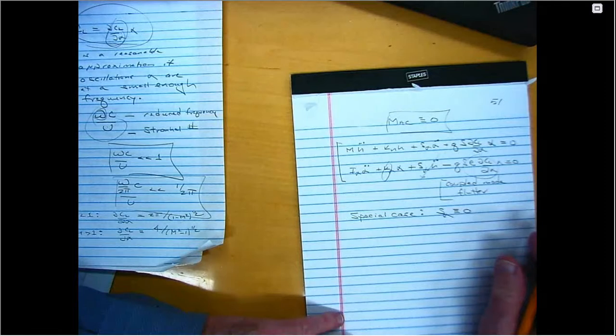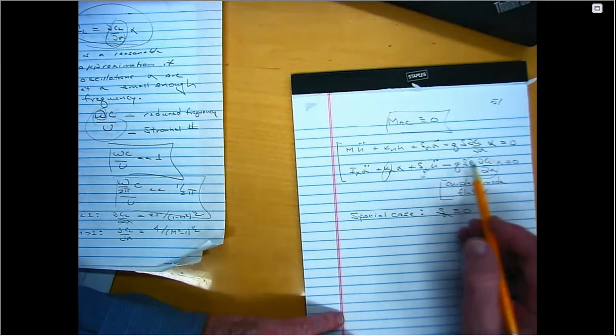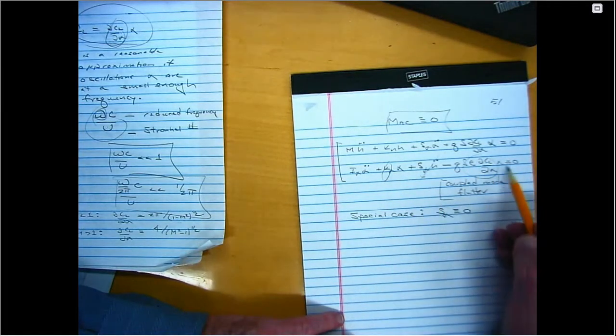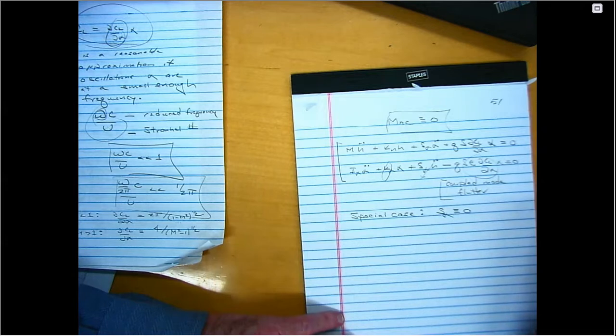What about single degree of freedom flutter? Well, I mentioned that the other day. I'll just remind you of this. If I have single degree of freedom flutter, the only way I can get that is if in this term, even with S alpha 0, in addition to this representation of the aerodynamics, I also have an alpha dot term with the appropriate sign of the coefficient.